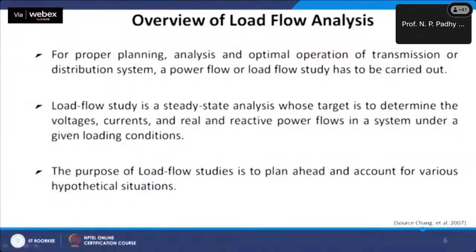Now the purpose of load flow studies is to plan ahead and account for various hypothetical situations. If the load scenarios keep on changing, how do I plan my system so that the voltage at each and every node does not violate the permissible variation, maybe 2%, 5% depending upon the utility.